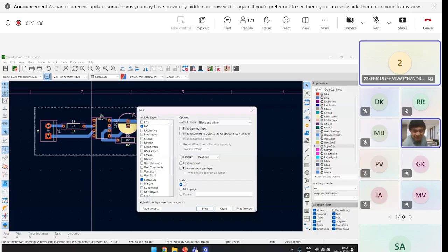No issue. So you can see that this is the microcontroller symbol that we will try to design as a custom made symbol. As I said, some symbols might not be available in the default library of KiCad. For this Atmega 328P, these are the pin out. You will need the data sheet of this controller actually.